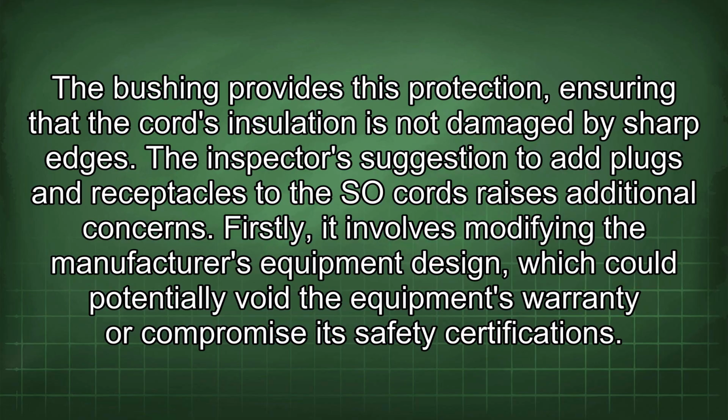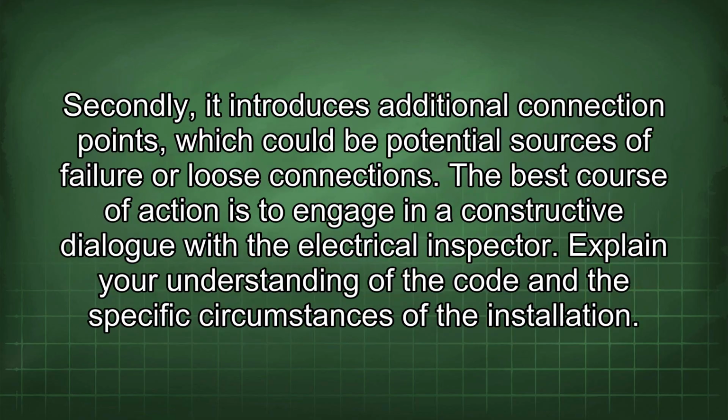The inspector's suggestion to add plugs and receptacles to the SO cords raises additional concerns. Firstly, it involves modifying the manufacturer's equipment design, which could potentially void the equipment's warranty or compromise its safety certifications. Secondly, it introduces additional connection points, which could be potential sources of failure or loose connections.